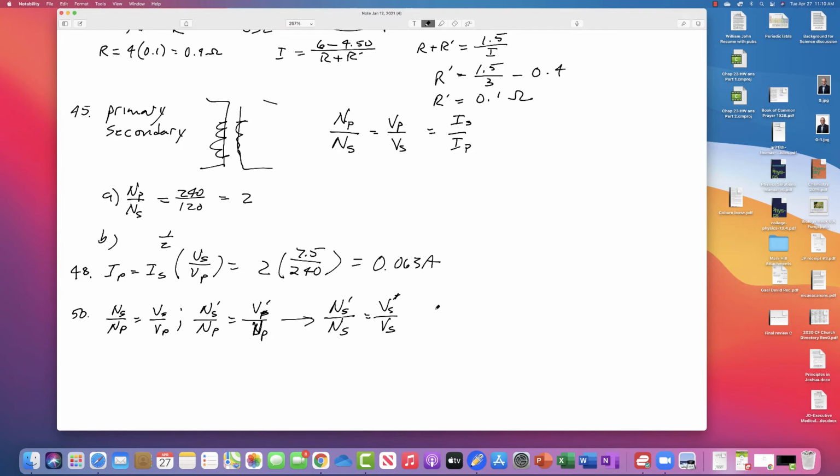Okay, so if we put in 750 kilovolts and 335 kilovolts, then the ratio, if you do that, is 2.2. So that means the number of turns, whatever the number of turns here was, you have to have 2.2 times as many here to get that same answer.